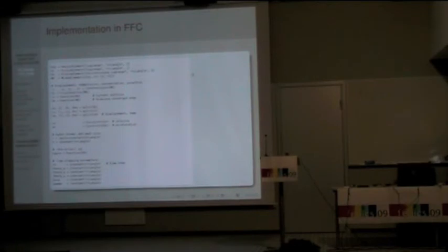This is the definition we use for the DG implementation with the facet normal and mesh size. And those are some time-stepping parameters. We use a generalized alpha method, so theta A can be different from theta U, and from theta B if we want also damping term in the balance of linear momentum, and from the parameters that we use for the evaluation of the Cahn-Hilliard equation at the midpoint and of the heat equation at the midpoint.